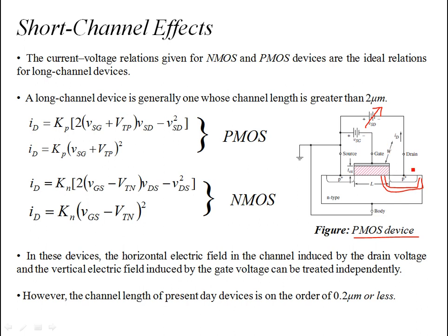You see, this is like a reverse bias PN diode over here. This is P, and then you have a negative battery terminal. So this is a reverse bias PN junction, and then again it has an N-type substrate. So there is reverse biasing with the substrate of the body as well. So this depletion region is growing with the VSD.